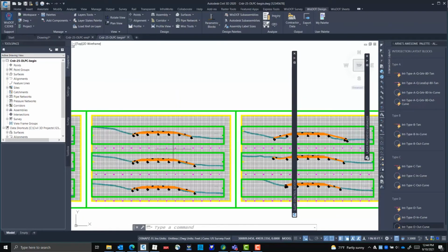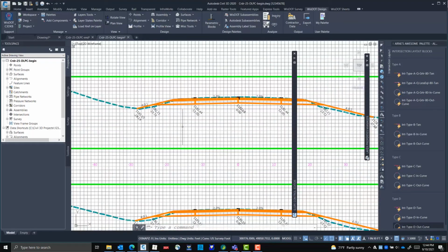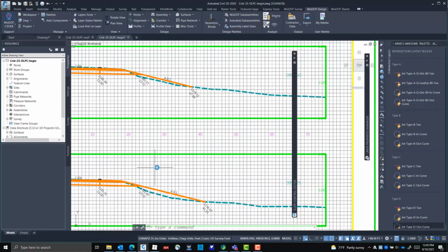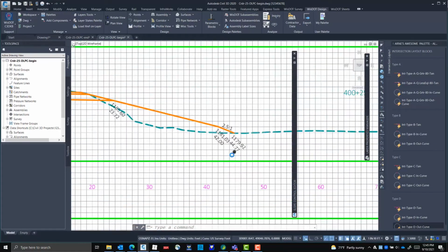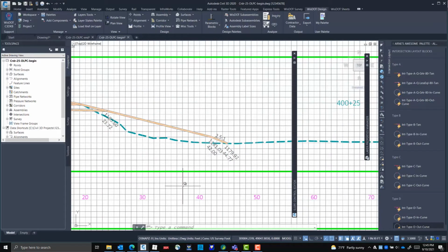But you can imagine, I'm sure for those of you who have done plenty of projects before, you can run into scenarios where you need to adjust the slope, you need to change from fill to cut, or fill the ditch to fill. Sometimes you might have a break point right here, like you say, okay, I've got my clear zone out at 42 feet, and technically that's right, but this is like a 3-foot link. I'm not going to have construction build that. I want to flatten this out to the same slope as my recoverable for constructability, because it's going to kick out my slope intercept like maybe a half a foot here. I don't care about that.